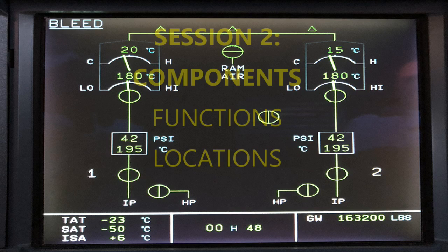All right. Okay, so that gives you an idea of what's involved with that precooler exchanger. Then we also have the transducers, because remember I said there are temperature sensors. We just talked about one, right? But also the transducers. So what transducers do we have? There are two of them: the bleed transfer pressure transducer and the bleed regulated pressure transducer. They're installed on a bracket in each of the pylons.